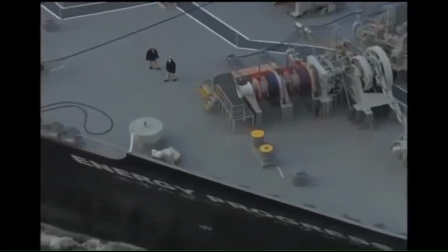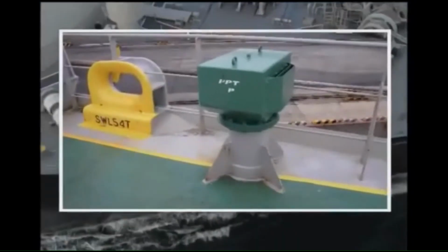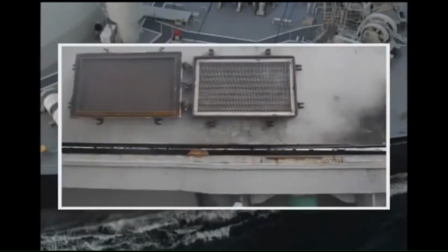Sticking of a tank's air vent and so forth can cause the tank to expand or shrink, which may damage the hull. Therefore, make it a rule to conduct inspection and maintenance in your daily routine. For ships with cargo holds into which ballast water is loaded, be sure to confirm that their cargo holds are ventilated.